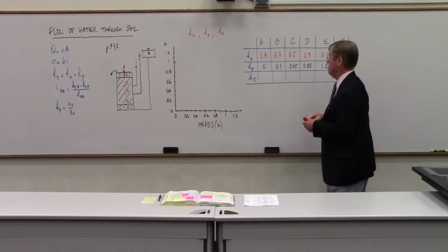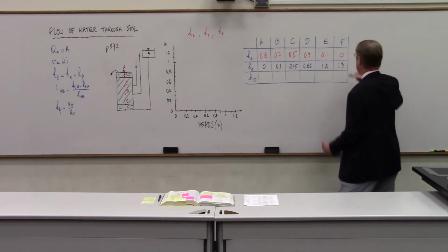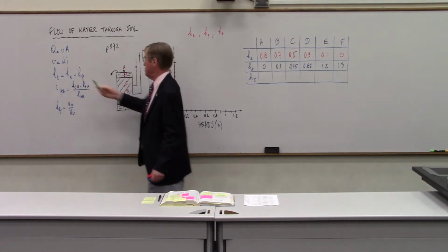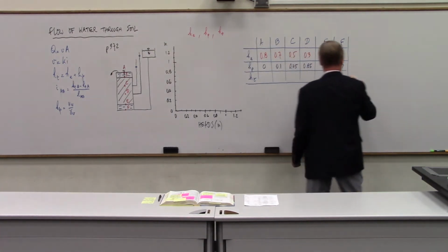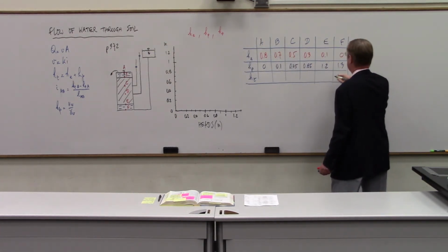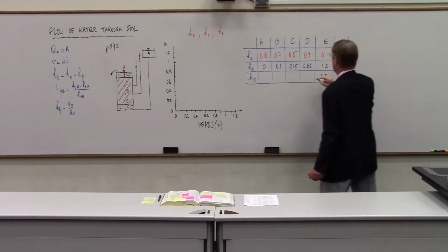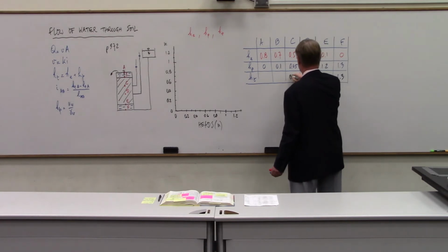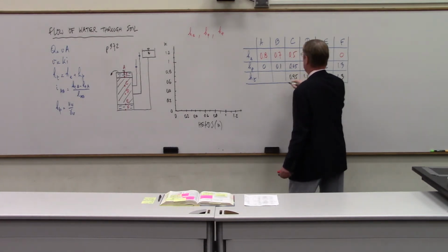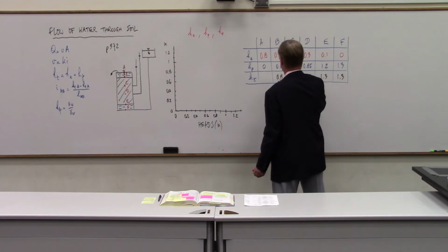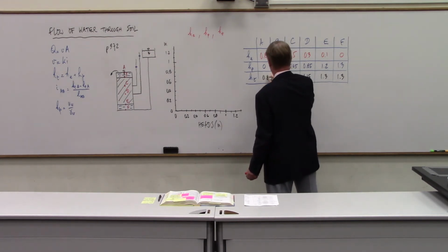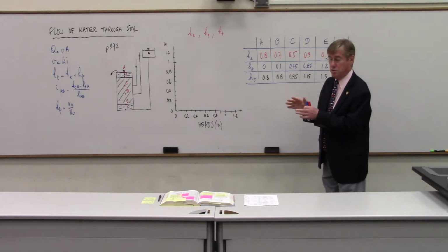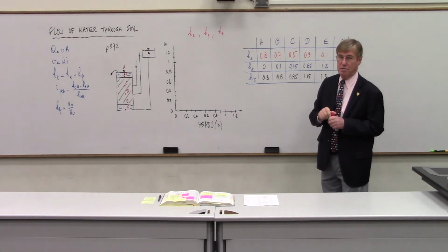And now, I simply add the two to get the total head, because total head is elevation head plus pressure head. So I've got 1.3, 1.3, 1.15, 0.95, 0.8, and 0.8. And remember that the total head is proportional to the energy spent by the water.